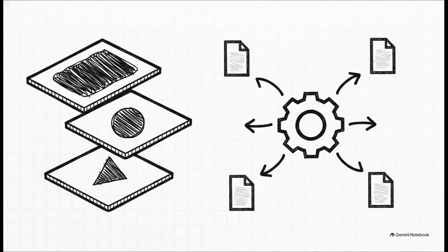But to truly utilize these styles effectively, you've got to be intentional. You should be applying specific, distinct styles to different elements of your drawing. I mean, your main titles absolutely shouldn't be using the same style as your tiny dimension numbers. Plus, you need to combine this with a robust layering system. Put these distinct styles on separate, dedicated layers for absolute visibility control. Because here is the magic trick.